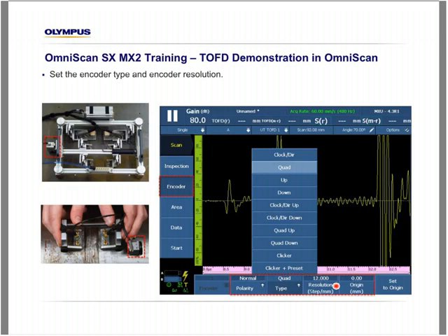If every inspector is using the same encoder with a different resolution, it's going to hurt repeatability. Again, all the commercially available encoders are dependent on the user getting a good grip and adjusting it correctly, but that number should not change over time unless there is really a problem with the encoder, the wheel is worn, or the rubber around the wheel has become distorted.